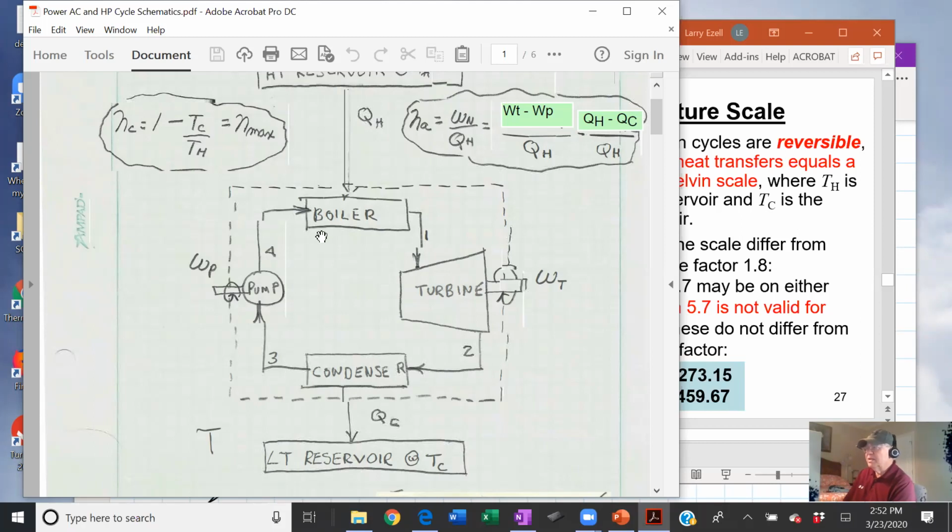And these are heat exchangers, the boiler and the condenser. They generally can be said to operate at constant pressure. So you go constant pressure through the condenser, but you change states from a vapor to a liquid, a low pressure, fairly low temperature fluid. Now you got to get it up to the higher pressure of the boiler, so you have to go through a pump. Pumps it up. It enters the boiler as a high pressure liquid, and the whole process continues.